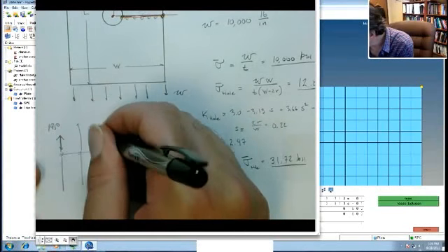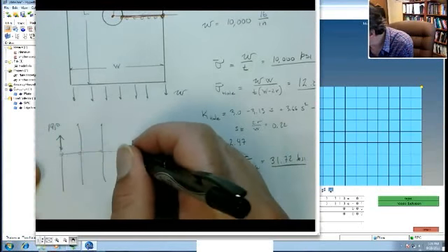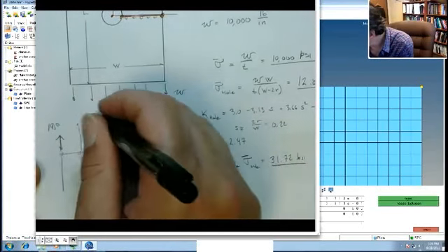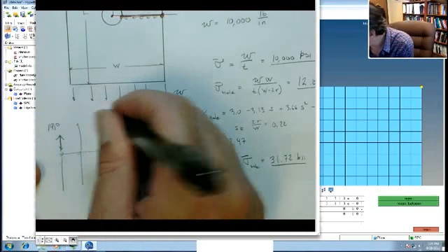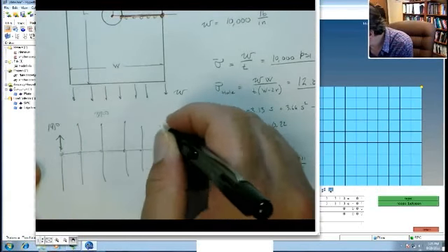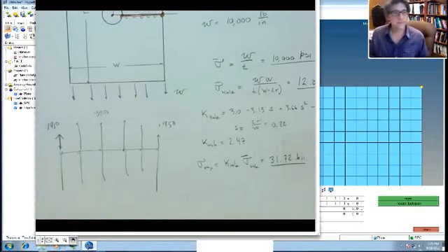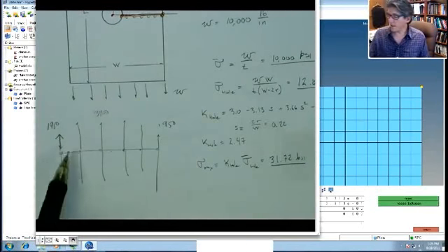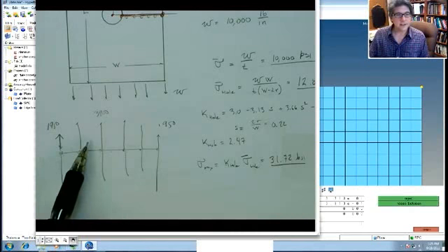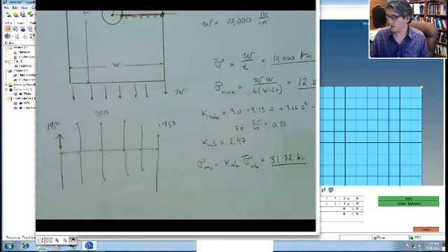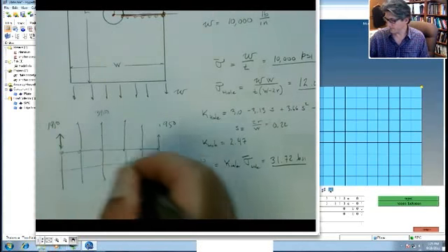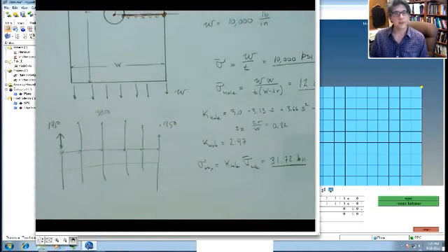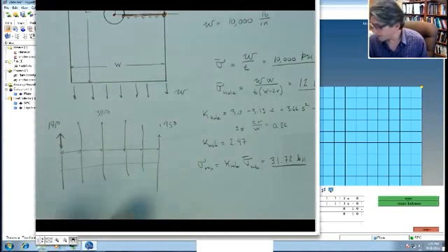On the ones on the interior, where you get contributions from two elements, they're all going to have 3900, and on this edge, it'll be 1950. Okay? And that's the way it works to get a distributed load. If you set them all to 3900, actually you have a little extra force, and you'll get a little stress concentration at the corners, and that's technically incorrect. We talked about distributed loads in class as well, but that's the way it goes.